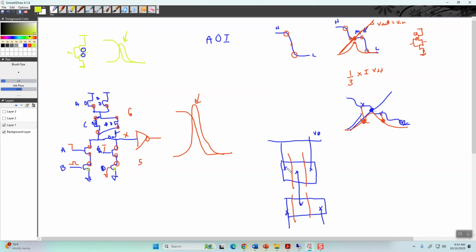And so for this one, there's an n-well around here, which is tied to VDD and it shorts it. So I have this area to charge and discharge, which is better to connect this way than the other way. Here it doesn't matter. Everything's got to charge and discharge. So you have an area here, an area here, another drain, and another drain.